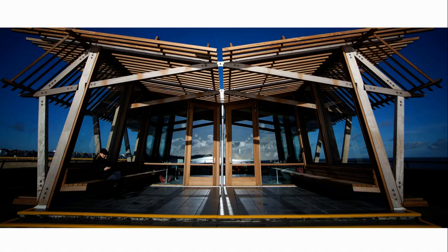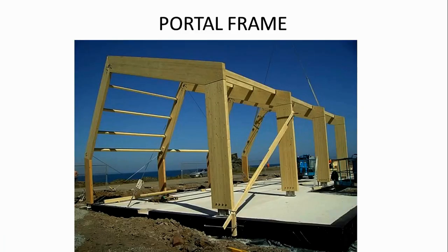Timber, again, it's not literally an A-frame, but you can see the same principles in operation, can't you? This is a relatively new project for a pier, a jetty. Now, I mentioned the portal frame earlier. The only difference here is that it's an A-frame effectively, but it's the depth of this structure. This is actually engineered timber. You can see it's not been cut off a log. It's a series of glue laminated timber sections glued together.